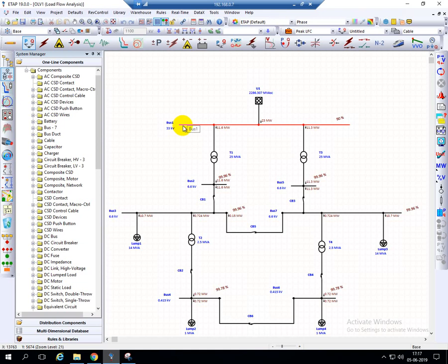And this bus bar is at 90%. When the bus bar becomes red in color, it's just an alert: this bus bar is in an under voltage condition, it has not fully satisfied the rated voltage. And we can see 99.96% voltage level at this bus, and this is the power flow. We can see the 11.6 here and here also the 11.6. Here we can see there is very little voltage drop or power loss.